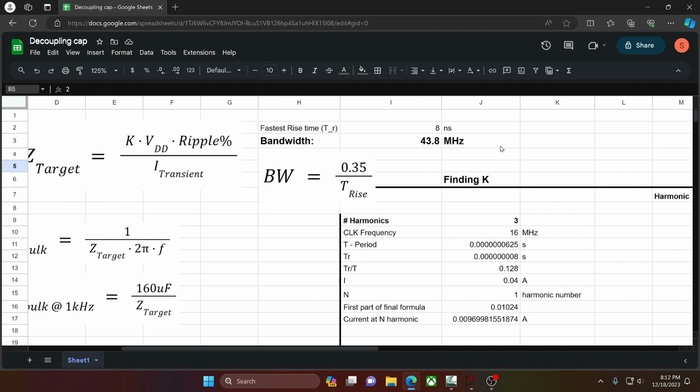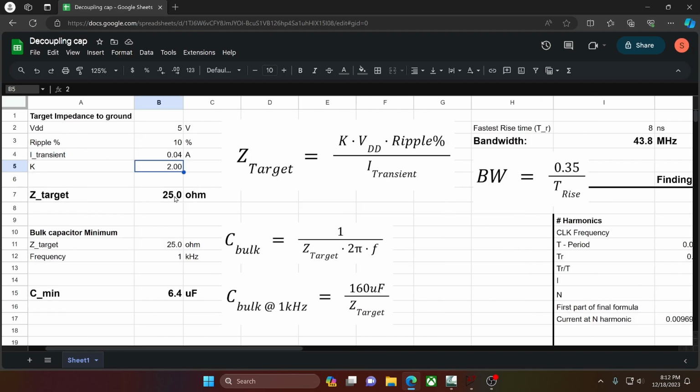Anything higher, we don't care about. So what he was saying was that approximately half the noise energy is going to be outside of this. Hence, you can double your impedance target. Half your impedance target. Double.